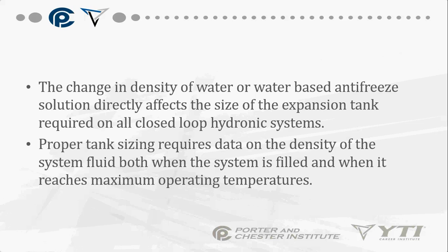To change the density of water, a water-based antifreeze solution directly affects the size of the expansion tank on a boiler. Because what does antifreeze do when we add it to the water in a hydronic system? It lowers the freezing point, so it lowers that water's ability to freeze, right?